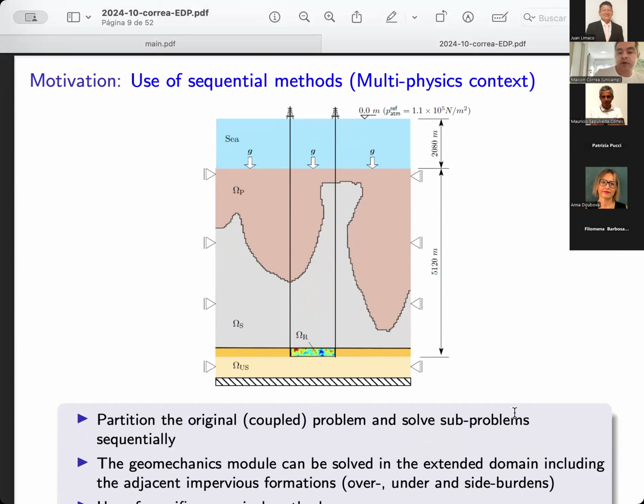And you may have different bubble point pressures, and this is really a non-linear problem. So since we are not going to use the saturations, because the saturation of gas we can't trust, it disappears sometimes, we are rephrasing the equations in terms of the component concentrations. So this is the form of the mass balance we are considering, because with this set of equations, we always have the concentration of gas. The saturation of gas may disappear, but the concentration is never zero.